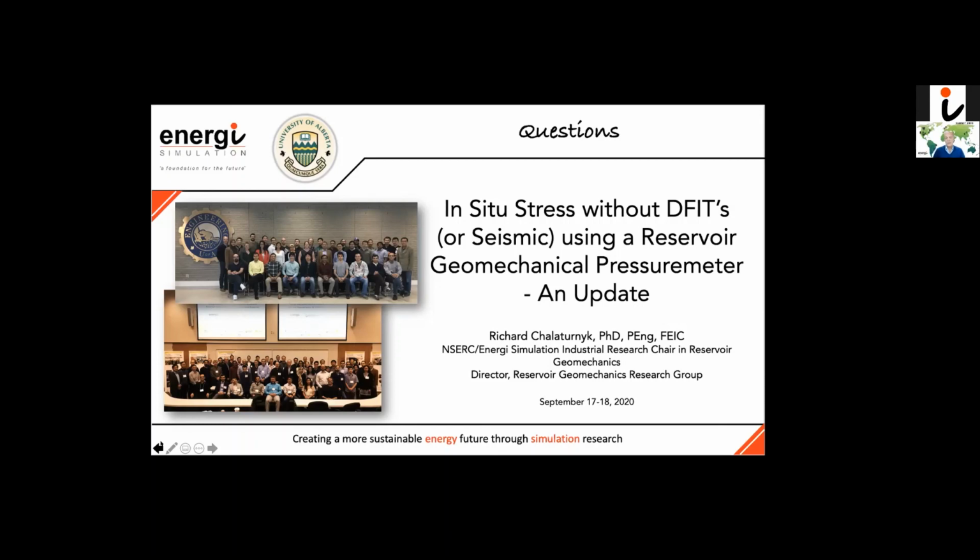Well, that's the whole idea about moving to the self-boring capability. But even in the pre-bored version, you need the full curve. So if you did a partial expansion curve, you likely would have some challenges. But by being able to move through the full expansion curve and the unload curve, it allows you to move the response of the rock out beyond the near borehole disturbed zone.